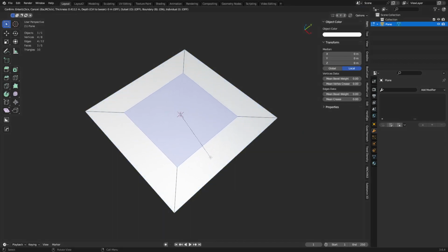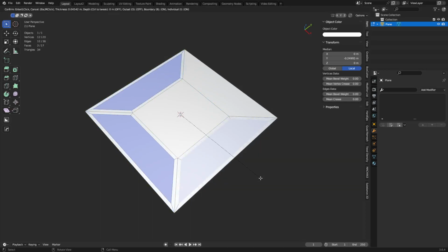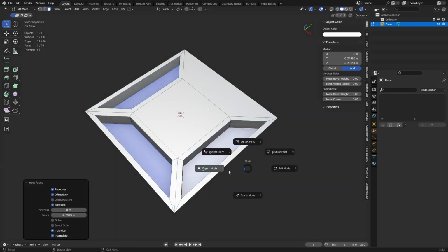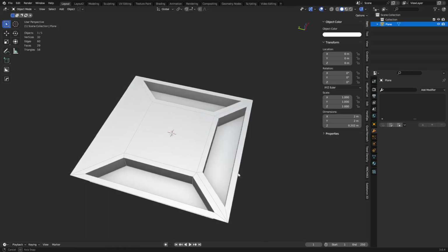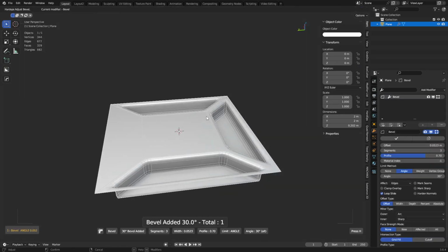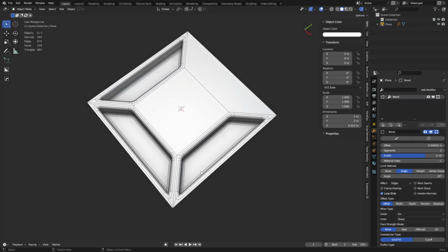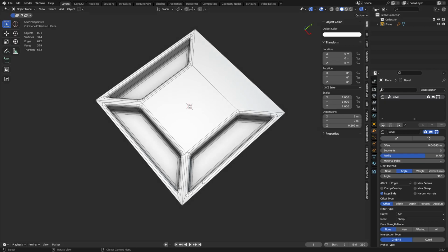Take something like this and inset it. You see what this is? When we take these three and inset them and press I, suddenly we've created those shapes, or now turned it into a form. Later on, you might bevel something like that, and you end up with some nice looking sci-fi stuff going on here. Just simple geometric shapes, basically. Nothing too crazy there to think about.